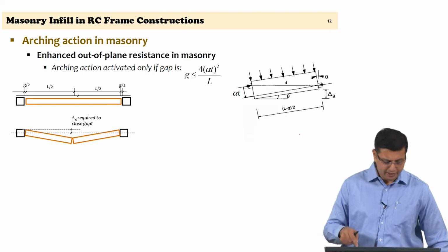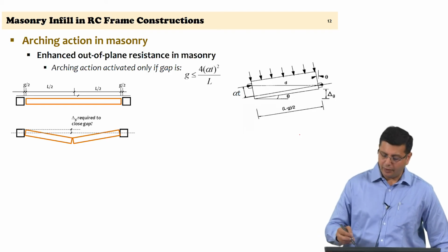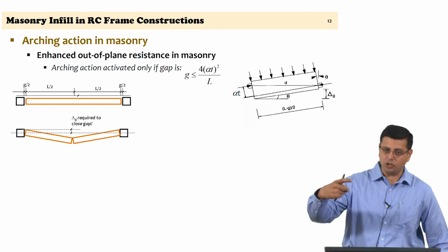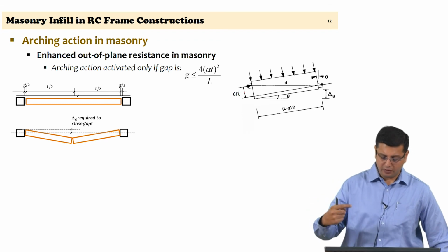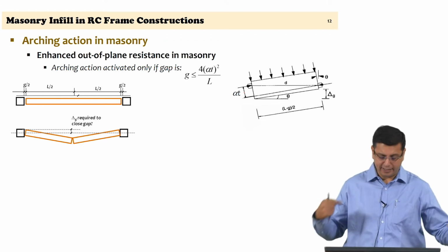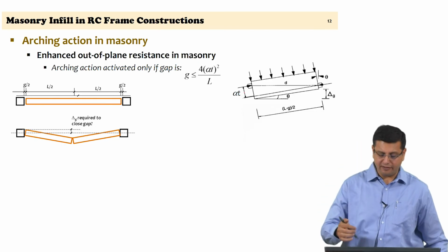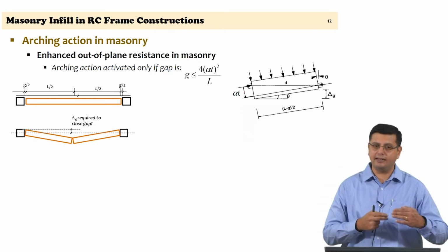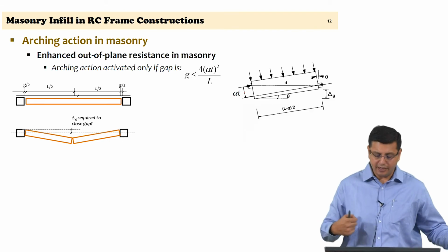So, primarily by looking at the geometry, alpha T is a percentage of the total thickness where the clamping force is actually acting, and this alpha T is to consider some amount of softening that can occur in the masonry due to the additional compression.